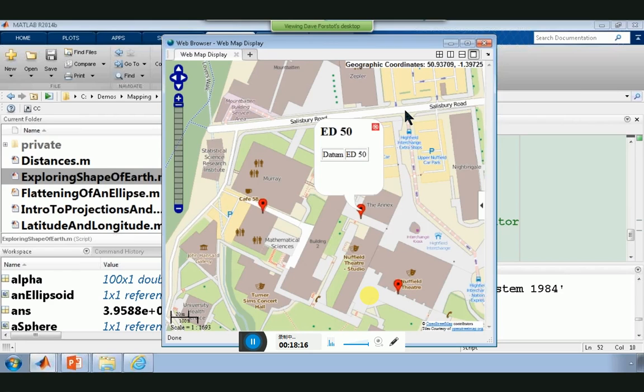Because even if we say these were very, very accurate measurements, error propagation from one to the next could result in very, very small errors accumulating, so that you had large errors when you get to a place very far from where that datum was defined. And so when you convert from one datum to the next, it's more than just an operation of potentially translating the center of that ellipsoid definition or scaling or rotating.